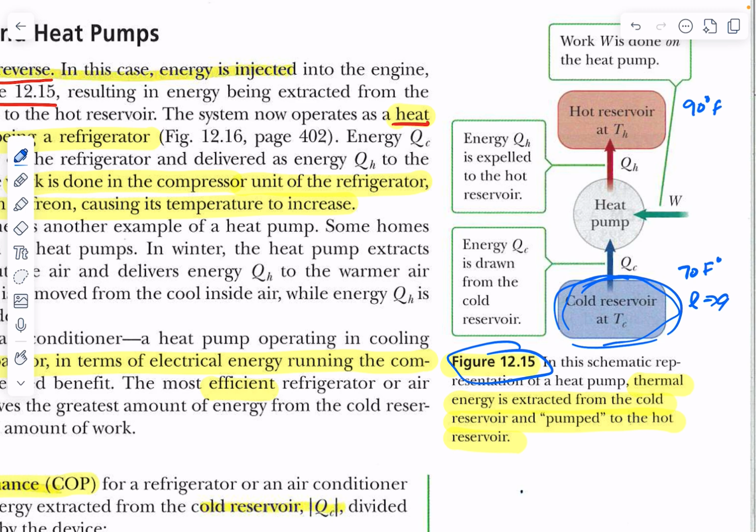And then that is pumped outside to your external air conditioning unit, and that's also where the compressor is. And the heat then is lost, and if you've ever been to an air conditioning unit outside, you can feel the warm air blowing out into the already warmer air of the outside. And then the compressor compresses that coolant back again, and it goes back inside to pick up some more heat. Now, a heat pump actually can also operate in the wintertime in reverse.